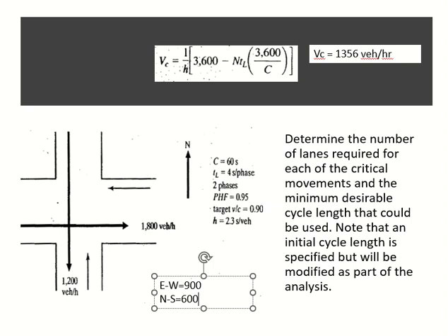No. I'm still looking for 1300. So now I will increase 1 lane in the east west direction. The total was 1800, now it has 3 lanes, so it will become 600. 600 and 600 is 1200. I was looking for 1356. So it's done. 3 lanes in east west direction, 2 lanes in north south direction.